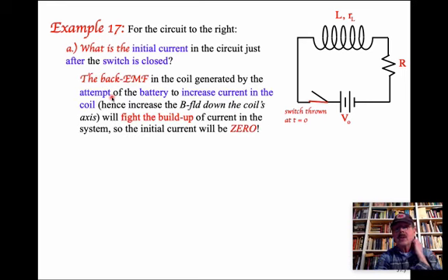Hopefully you thought through this and thought, okay, that back EMF is going to get generated. It's going to fight the buildup. The initial current is going to be 0. By the way, I didn't mention this before, but this induced EMF that fights the increase in the current is called a back EMF. It's an induced EMF, but it's actually called a back EMF by the geezers.